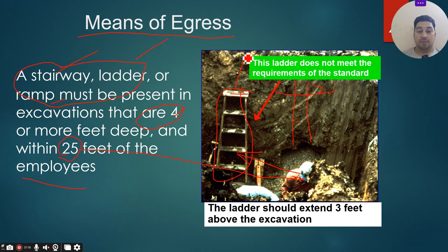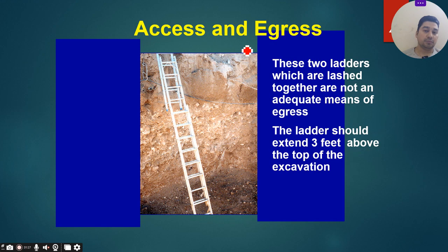So 3 feet from it will go till here, till this line, and from here also 3 feet more height you have to give to the ladder. So the proper ladder should be used.